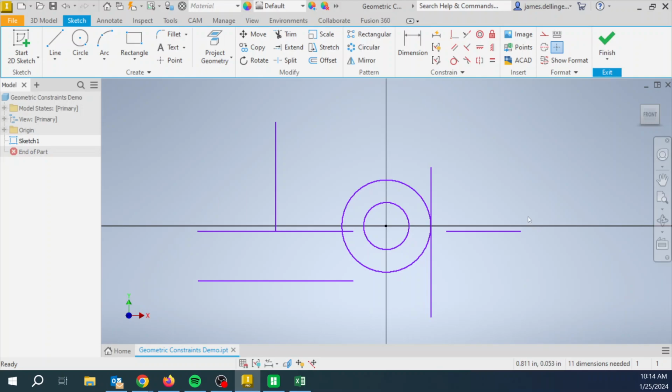All right, now we all have a giant mess on our screen. It's handy to delete it so we can do the next thing. The way Inventor selects so we can delete is kind of neat. Let's click and drag to the right, and you get a red box. Just go over a couple of them completely and then some of them not completely. When you click and drag to the right and it turns red, only the things that are wholly inside the red will be selected. So in this case, I'm going to select those 3 lines.